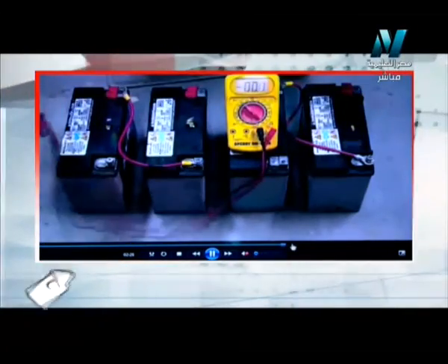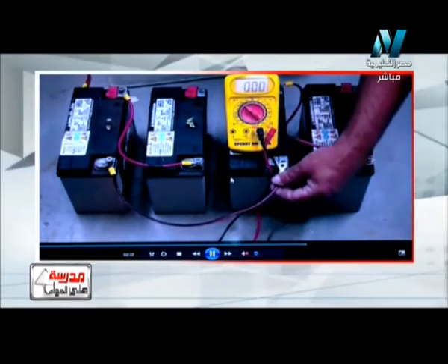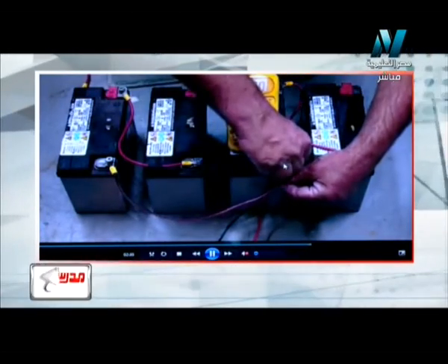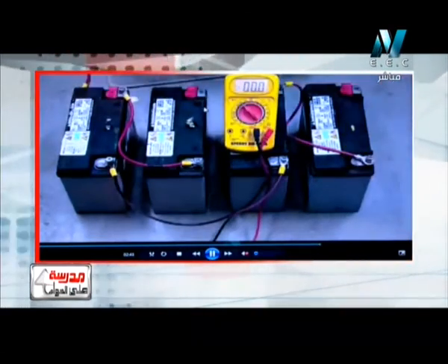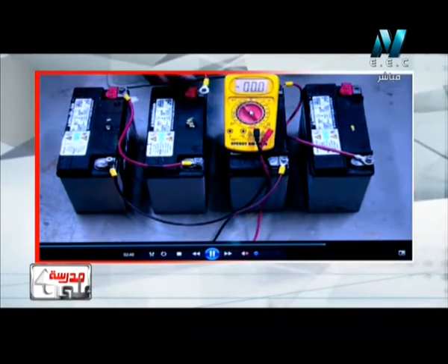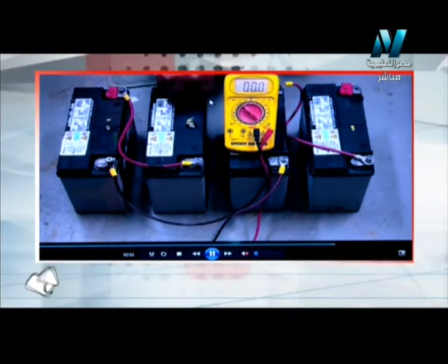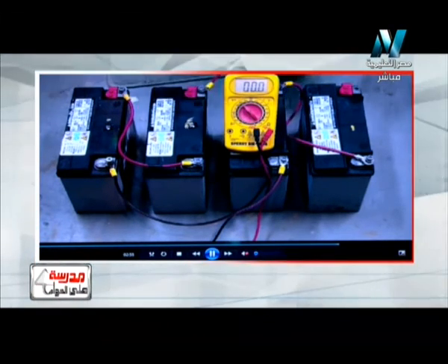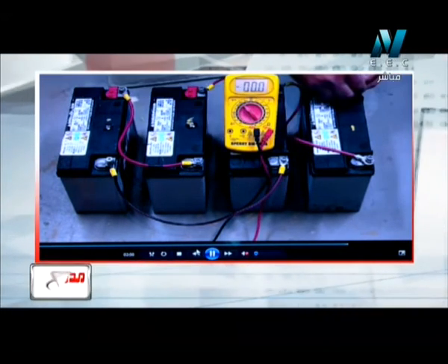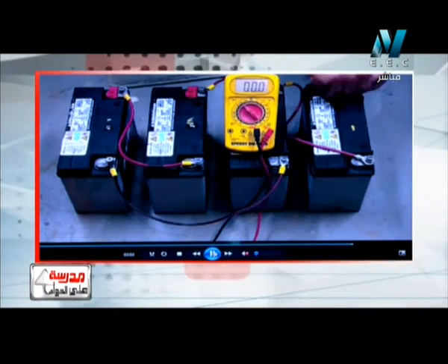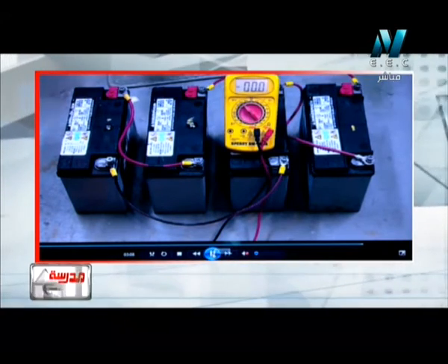In series it is positive with the next negative. But how come here we have to change? Look, positive with positive together. So all positive poles are connected together, and from the other side we connect all negative poles together to obtain the minimum electromotive force of the battery in the parallel connection. So now, dear students, we know the difference between series and parallel connection, according to the value and according to the way of connection.